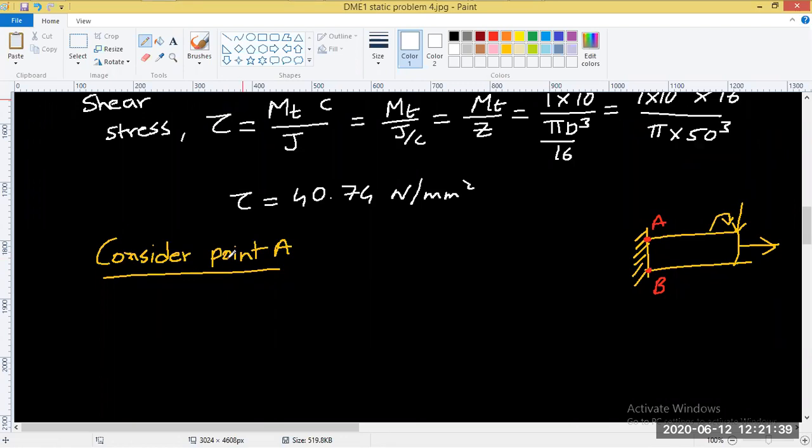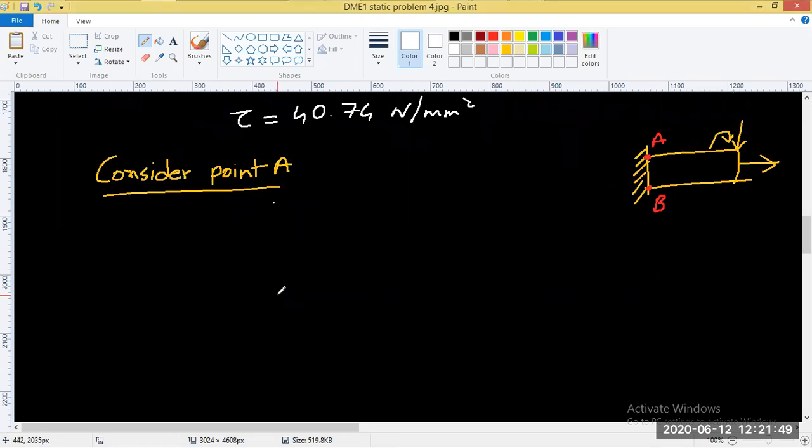That's the only way you can link all these three kinds of stresses, right? So let's find the stress due to the axial and bending. I'll say sigma is equal to sigma A, which is axial, plus sigma B, bending, the sum of both kinds of loads.